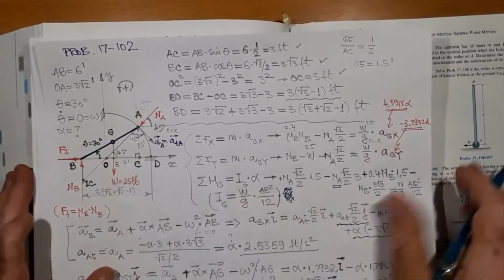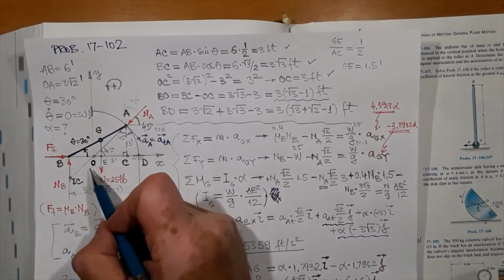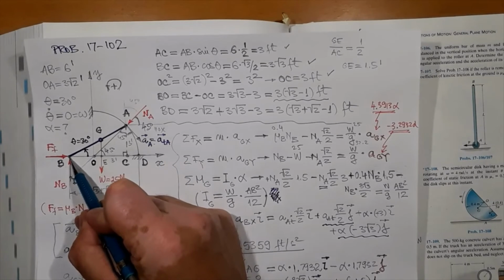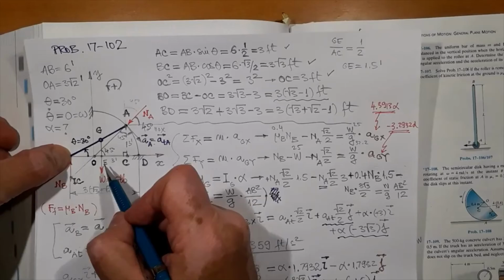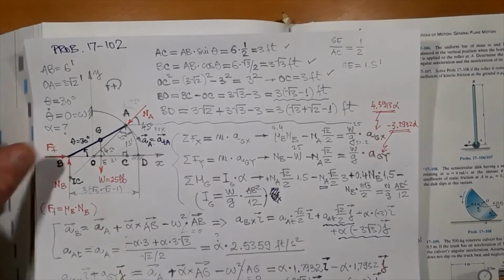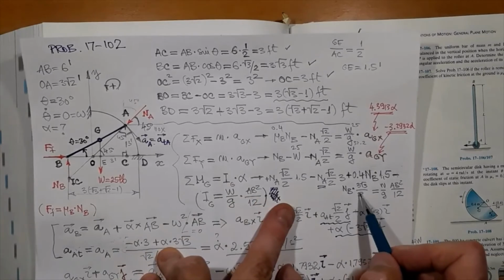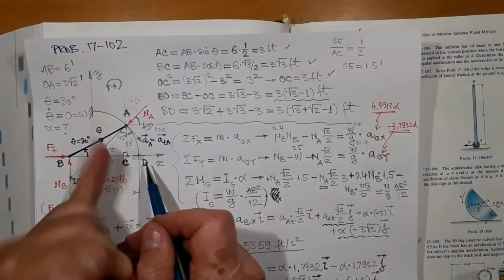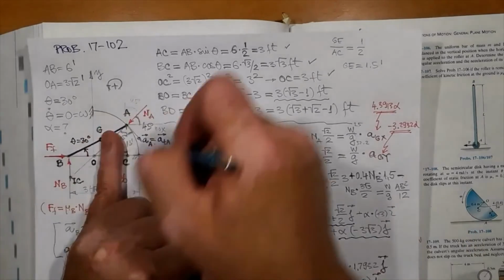For some reason I was combining some of the moments about B with that of G. And really, it's a slightly better alternative if you sum moments about point B. All you need to do is just take the mass moment of inertia of the rod about point B, and then the friction force and NB do not have moments. But I started with sum of moments about G, and I'm continuing. So where was the mistake? I had a moment about weight. Weight does not create a moment if I sum about G. Rather, I have a moment caused by the friction force, and that's a positive moment, counterclockwise.